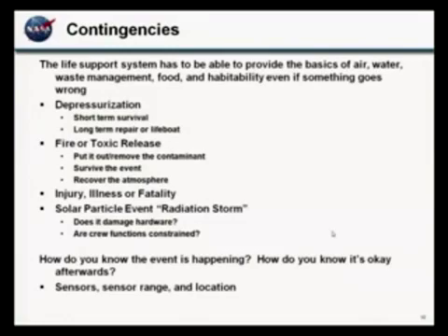So depress and feed the leak is also one of those things that can drive you to maybe not different functions, but different technology choices and different system sizing, right? The function is always provide oxygen, but provide 50 pounds of oxygen an hour for however long is considerably different than provide 4 kilograms of oxygen a day. Your electrolysis system is not going to be sized to pump out enough oxygen to feed a leak. So you better be able to provide it some other way.